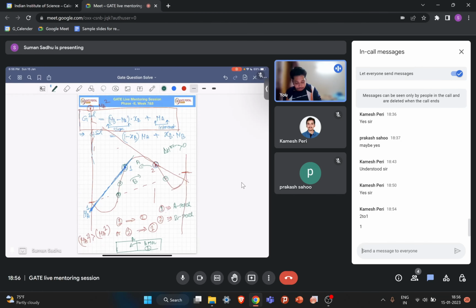So if you have this composition in your phase diagram, it will automatically move in this direction and split into these two compositions, because it will minimize your free energy. This process will continue until you get the same chemical potential. If you draw a tangent covering this point and this point, you get a common tangent for these two points. So what is the meaning of a common tangent? A common tangent means this phase and this phase will be at equilibrium.